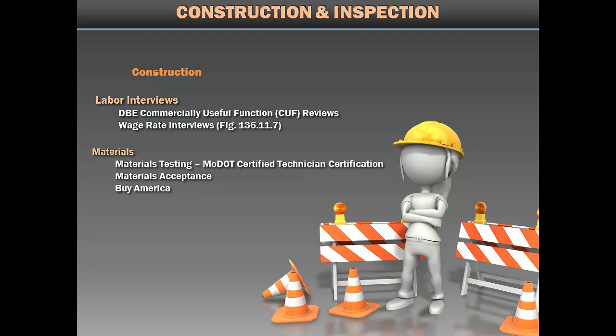You make the phone call to the supplier and you finally get the news. The supplier cannot provide the mill certs because they were misplaced or lost. Either you have to tear the bridge deck off and remove the girders from the project, or you will be forfeiting every penny of federal funds on the job. You cannot just make the steel item non-participating, so don't take the risk. It's not worth it. Get your certifications before you accept the material. If they don't have it on the delivery, send it back.